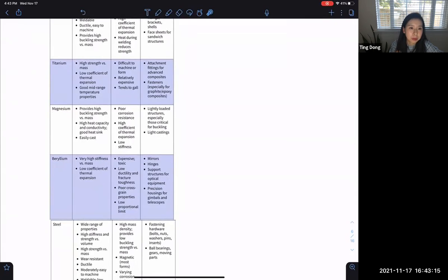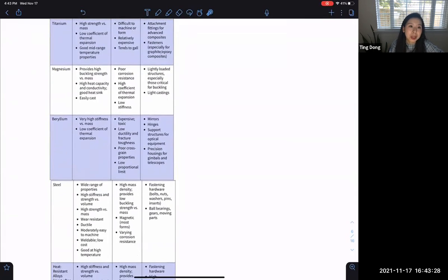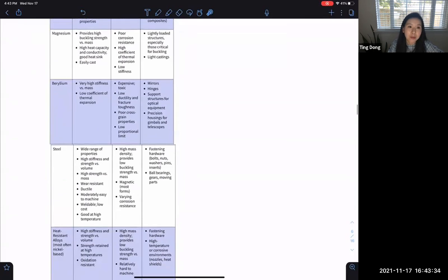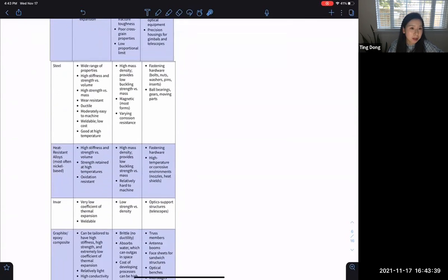So if we use aluminum for the re-entry or entry, we probably need a much thicker, heavier heat shield. But if we use steel, we can actually make our overall structure lighter because of the thermal conduction. And of course, they originally planned to use carbon fiber composite, and they changed to steel probably because of cost.